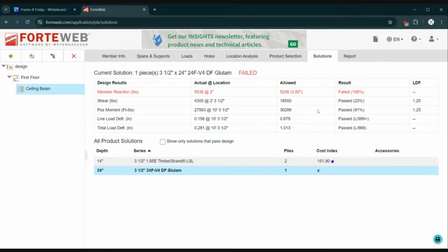What's going to fail is the wall at the beam. And that's because we could only put this much weight on the end of the wall, but because of the way we're loading the beam, there's actually this much weight on the beam. So it's too much. So what do we do? You have to increase the contact patch between the beam and the wall, because you just have to spread the load over more area. Or you pick a different wall.